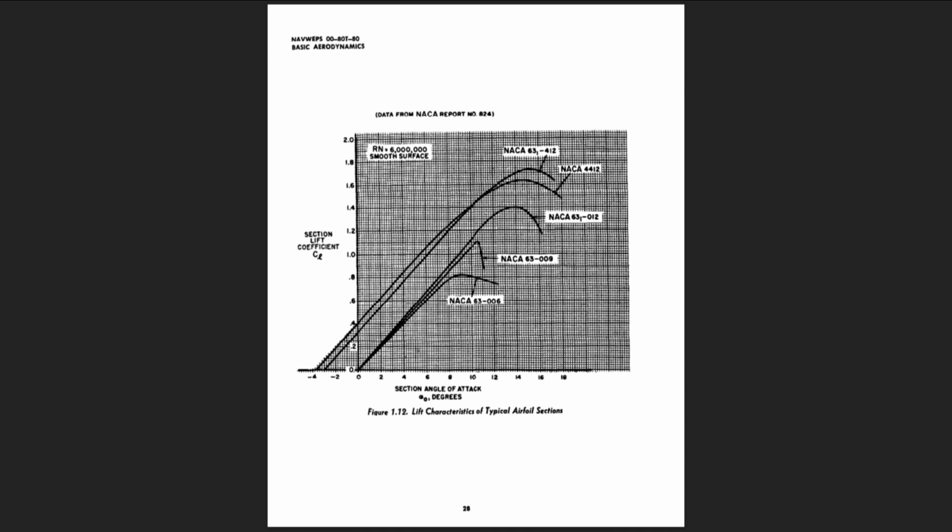Evidently, lift curve slope is not a factor important in the selection of an airfoil. An important lift property affected by the airfoil shape is the section maximum lift coefficient, lowercase cl max. The effect of airfoil shape on lowercase cl max can be appreciated by comparison of the lift curves for the 5 airfoils of Figure 1.12.